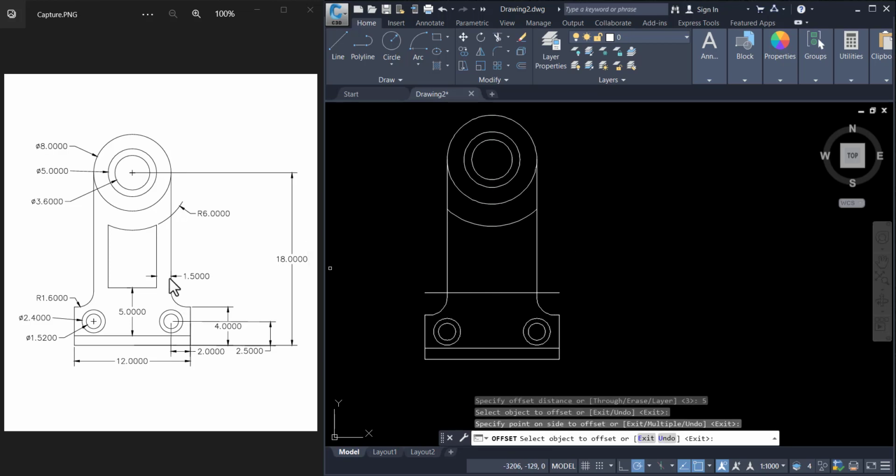We want this particular place from here to here is about 1.5 meters. You can see it here, from this line to this point is about 1.5 meters. So what I will just have to do, I'll escape, click on your offset tool again, okay, we want to offset it through 1.5, all right, click enter, this is it. Do the same thing to this other side, this is it, you escape.